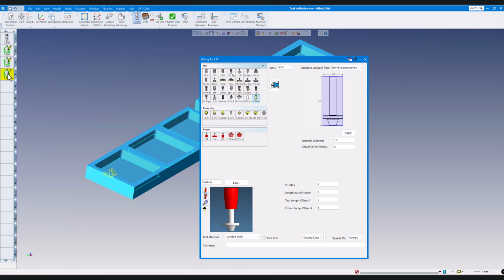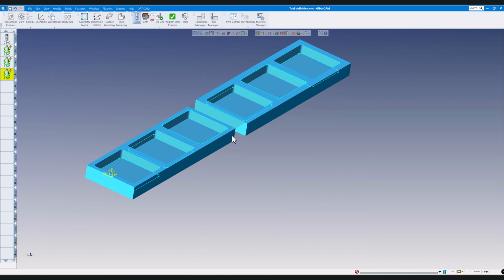Then the last tool, same form tool, this time drop down monotonic profile. This time it's looking at the outermost shape and all the way to the top. So if you told it it was going deeper than from the bottom here up to here, then everything would be considered its 1.5" diameter here. And let's show you that as well.